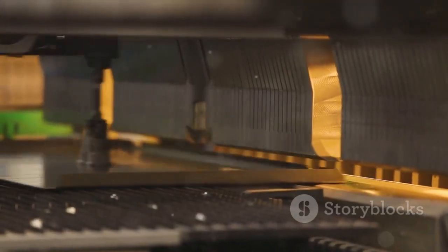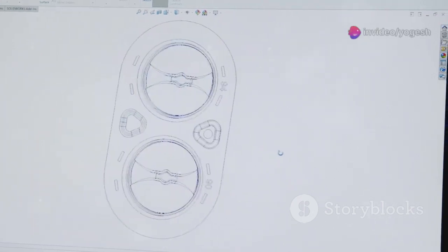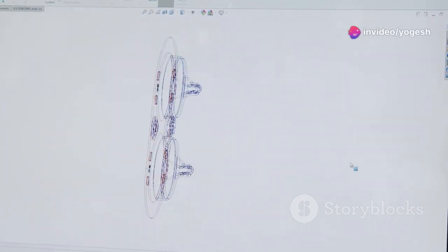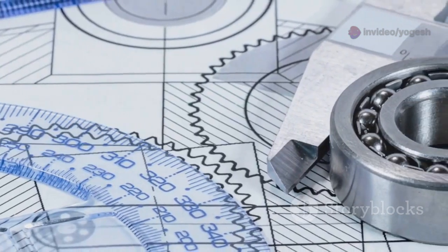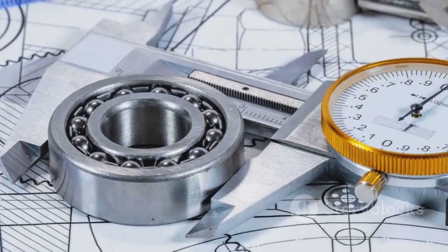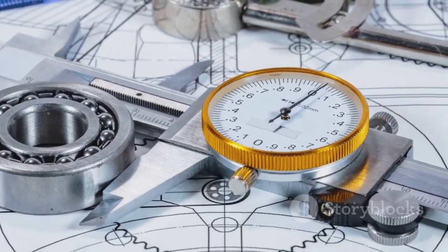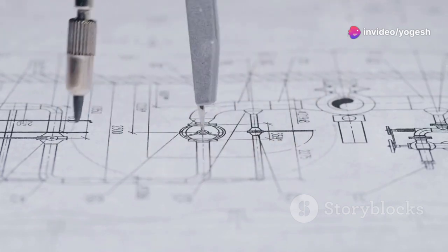Unfold the box using the flat pattern tool in your CAD software. Carefully inspect the flat pattern for any errors or overlaps that could cause issues during fabrication. Add a general tolerance note of plus or minus 0.25 mm to your drawing. This ensures that all dimensions are achievable and that the parts will fit together as intended.